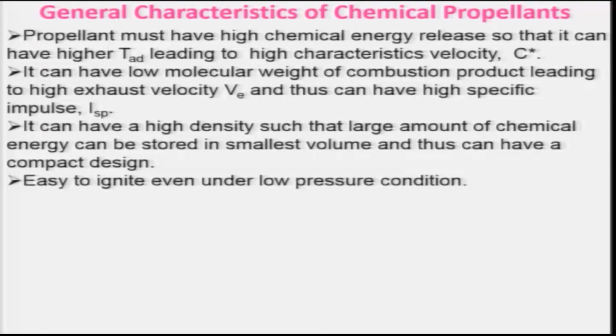It should also be easy to ignite even under low pressure conditions, because we have seen multi-staging. In multi-staging, ignition takes place at high altitude and low pressure, and keep in mind that it is very essential to ignite quickly, otherwise it will miss the mission path which is supposed to be adhered to.